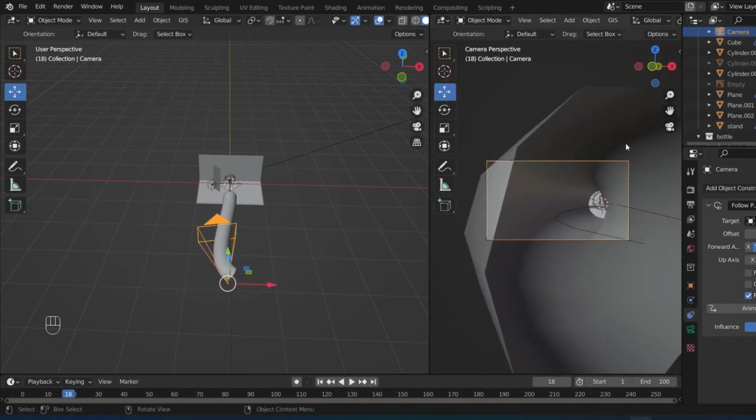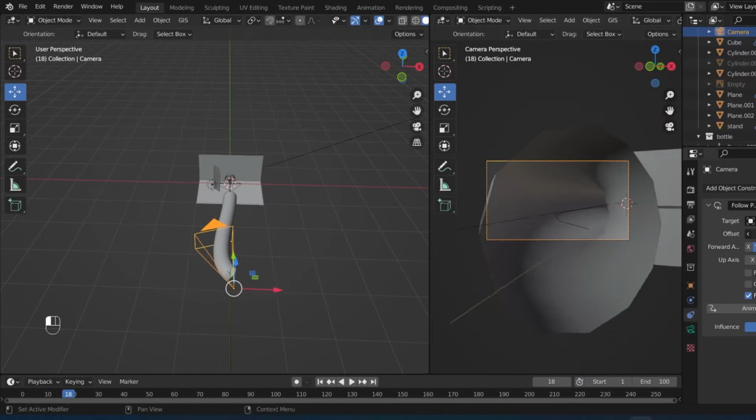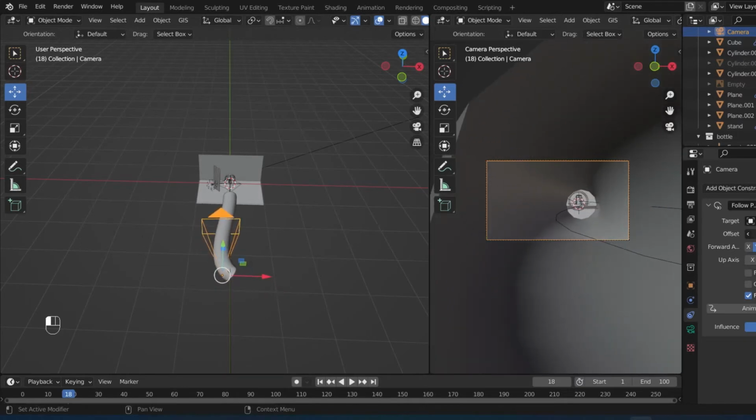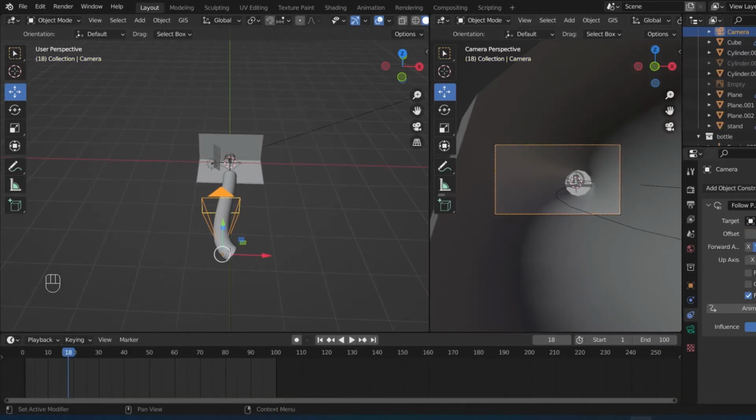Okay, so this part is clipping in over here, and I don't want that, so we can just start the animation from here, or you can also decide to scale this up, but I don't want to do that. So okay, from here, yeah, this is good. So let's set, I just clicked here to add a keyframe, and this is our timeline tab. This is what we use to animate stuff, and we use keyframes to do that. So this is the keyframe I just added. If I click it goes, if I click it comes back. So this is where I want it to start from, and I'm going to bring this all the way to the first frame.